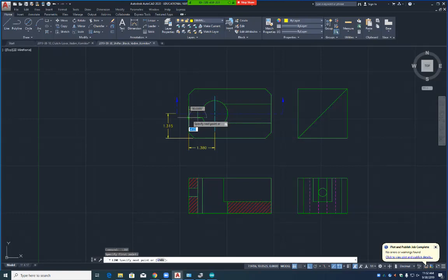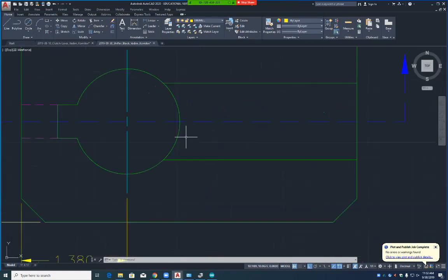Let me ask you a question. I come in here and my center mark, now remember, this should be a 16th, right? Everyone okay with that? How long should this be here? The up and down one should be an 8th, right? Now, is that proportionate there? So what do I have to turn off? You put that little X right in the center, right? That's called the center mark. How can I turn the center mark off?